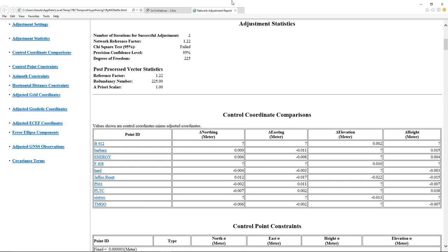If the number is less than 1, it means that maybe you put in too tight a value. I told it I could turn angles to 5 seconds, and really my observations aren't changing by more than 2 seconds. So if it's less than 1, that means that you've predicted too large an error for your observations. And as I get to scaling, I'll talk a little bit about your second point, Boris.